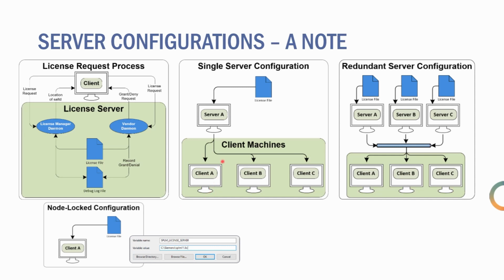However, if you have a mixed license where your node lock license configurations are part of your normal license file, then this would be a normal port at host location for the value. So it would be port 29000 at the host, the license server name. And then it would read in the machine ID to make sure that it will validate against the license.